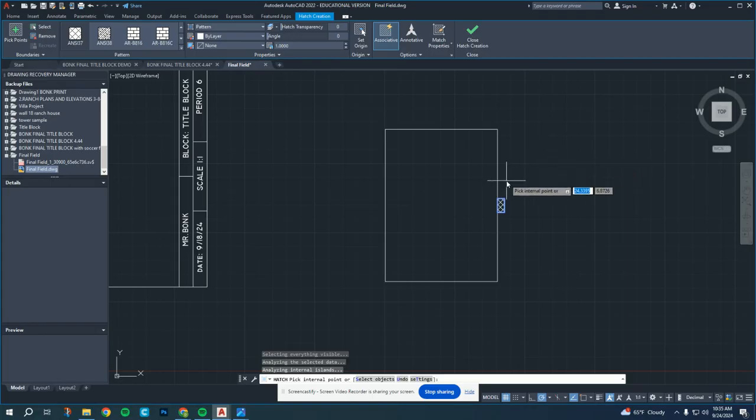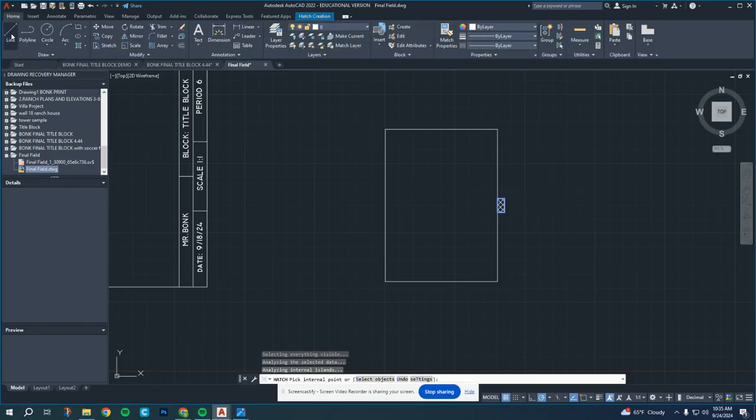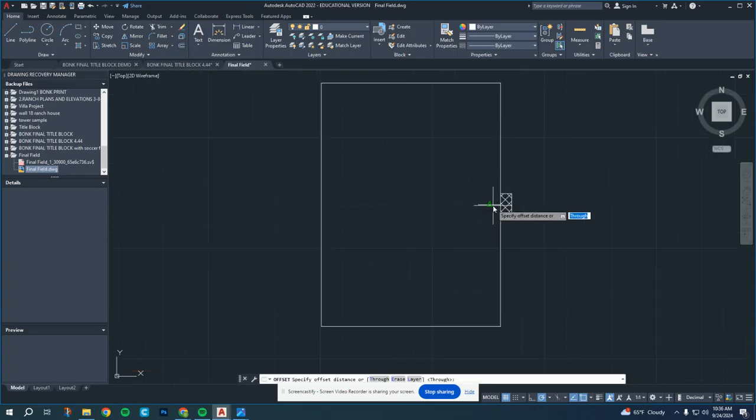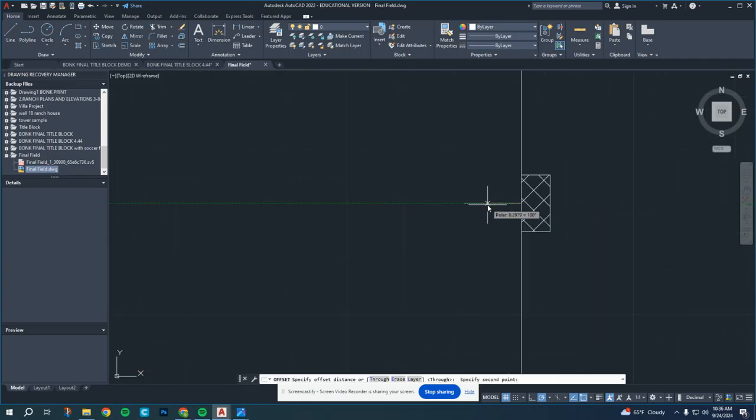Now I'm working on the field net that's going to go around. I'll click home. Get my regular tools back here. I'm going to start off with a 1/2 inch line. This line is going to get offset. The width of this up and down is 1.5 inches, so half of that is what I need to offset. I notice people clicking the middle or object snaps when you try and do the offsets.